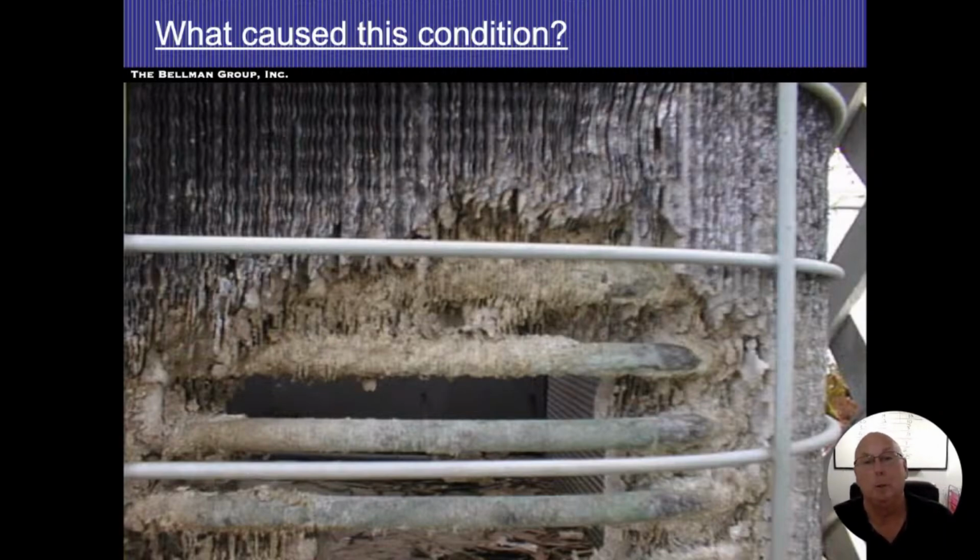All right. So, but the tubing itself is where the refrigerant runs. And then those up and down fins, you can see how tightly spaced they are together. So we get a lot of airspace that's touching the metal that's on there when it runs through. We do have to keep those clean.